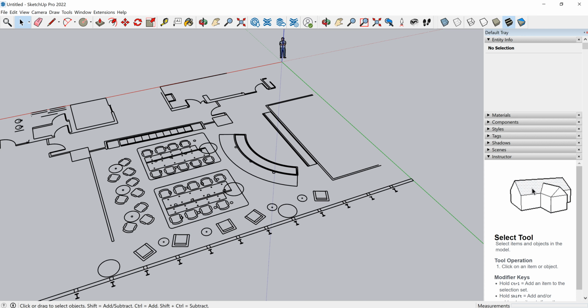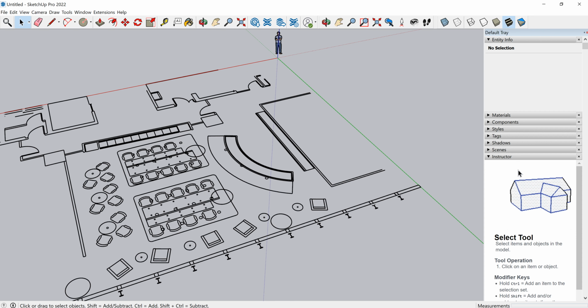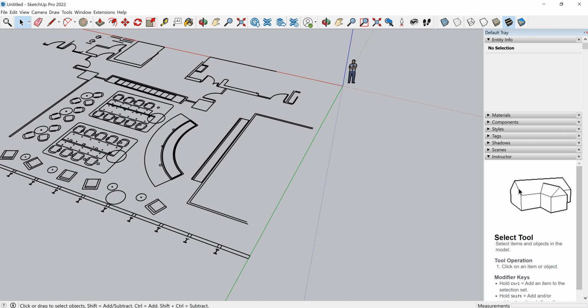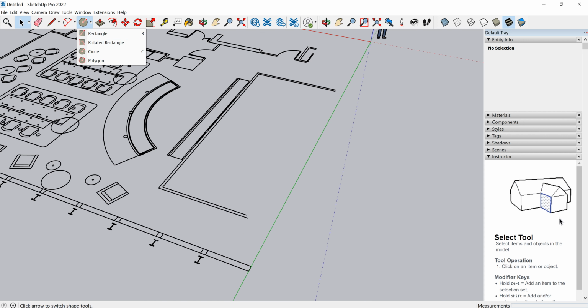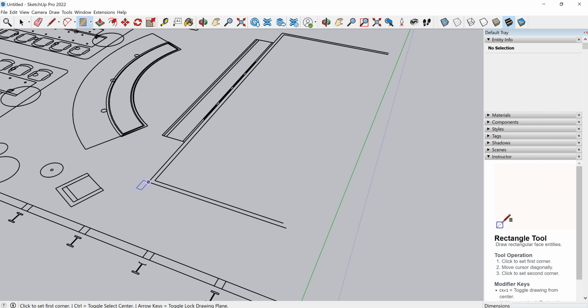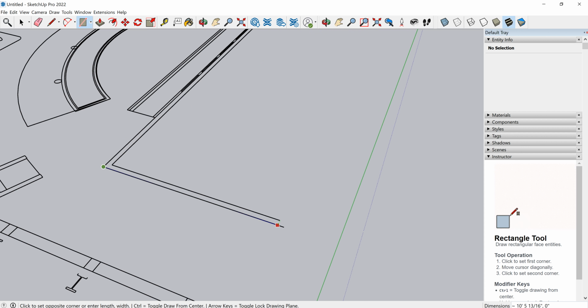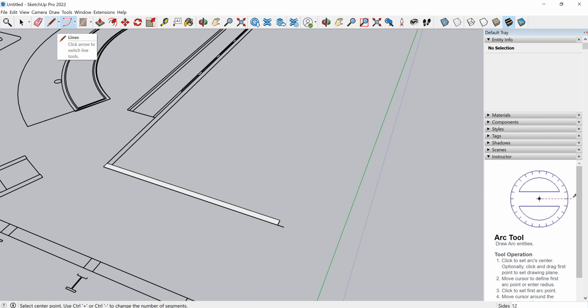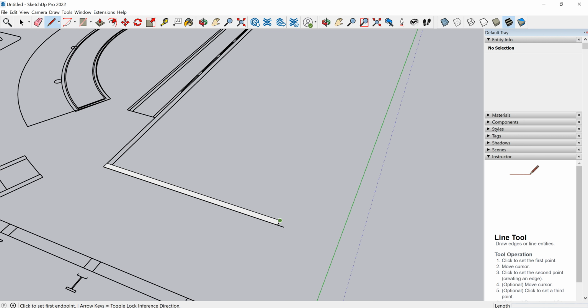And the reason for that is there's what's called stickiness in SketchUp. So as I start explaining this, I'm going to start drawing and not waste your time. And stickiness is one of these things where an object and another object can become attached, and it's not an easy thing to detach. 2 planes kind of collide and become one. Because they're not grouped, they are basically stuck together, and it does not make life easy in the sense of editing and building. And so for the most part, I'm going to show you a little bit of that, or preventing that.